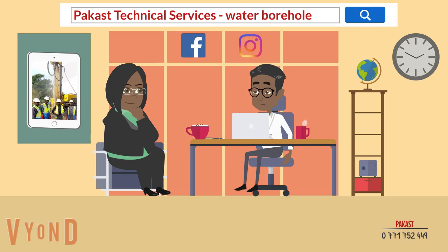All things considered, when we talk about the well rate measurement, it is extremely important to establish the static level of the water mark. To do this, you should not touch the water for at least an hour. It is during this time that a column of water equal to the static parameter will be collected. Then the well is emptied and the time in which it is completely emptied is recorded. After that, they again wait until the well is filled, and measure again. If the indicators for several stages of water pumping are similar and correspond to the customer's daily consumption, then the drilling project is